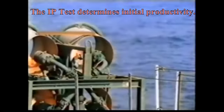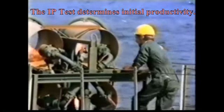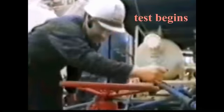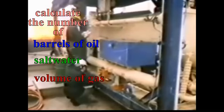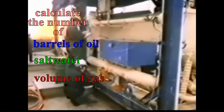The initial potential test, IP, determines the initial productivity and is done over a period of from 24 to 36 hours to calculate the numbers of barrels of oil, of salt water, and the volume of gas that can be produced during this 24 to 36 hour period.